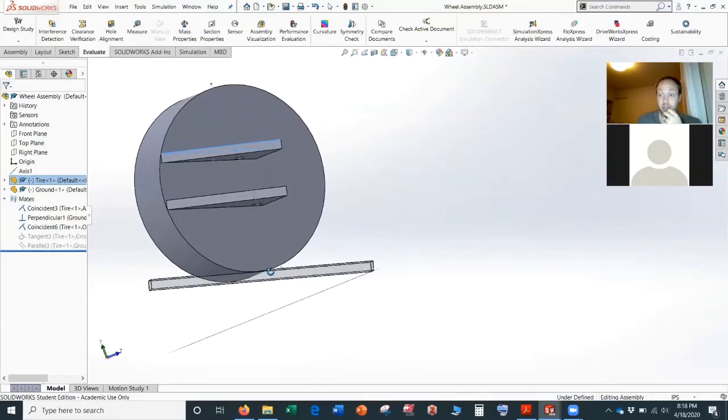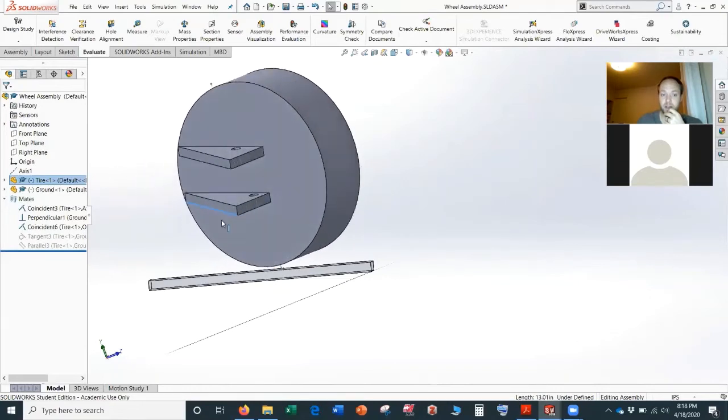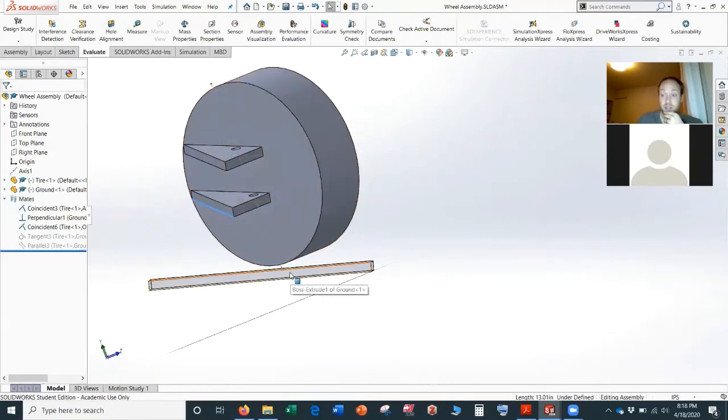So this is one of the big reasons to have some caster. So, for example, right now, you're making a right-hand turn. What this does, because this tire lifts up and the opposite is going to happen on your right tire, it's going to go down into the ground. So what that basically does is your right tire is actually going to move up a little bit, compress the spring, and it's going to shift weight. So it's going to move the right tire up. It's going to compress the right spring, right? As it needs to go into the ground.